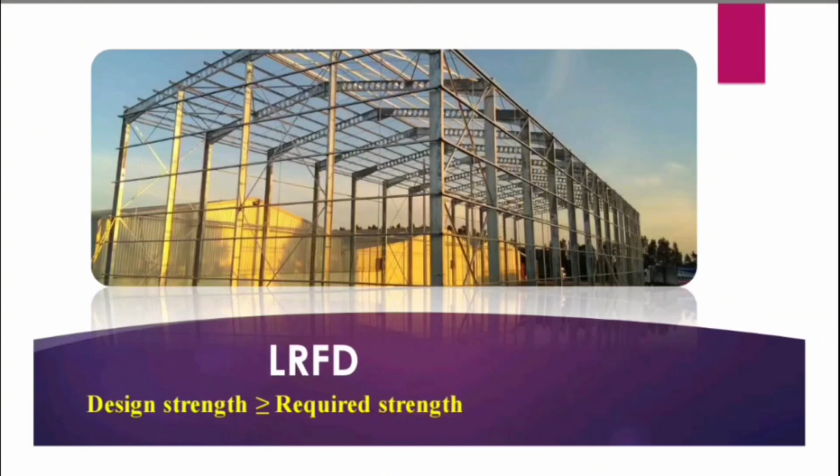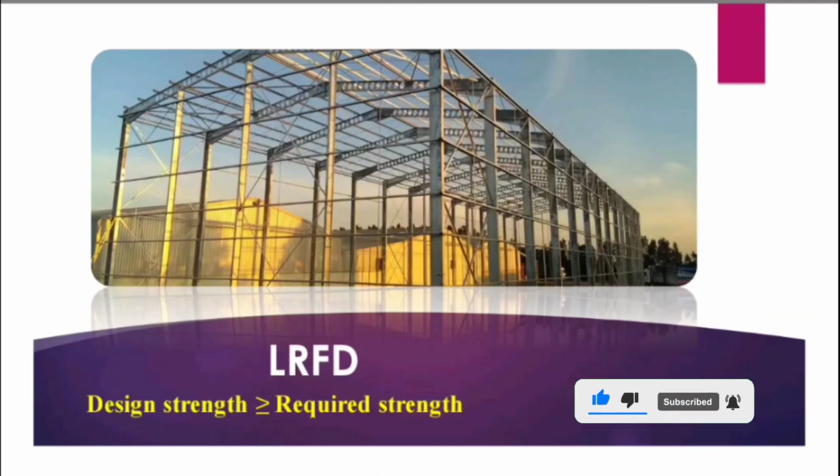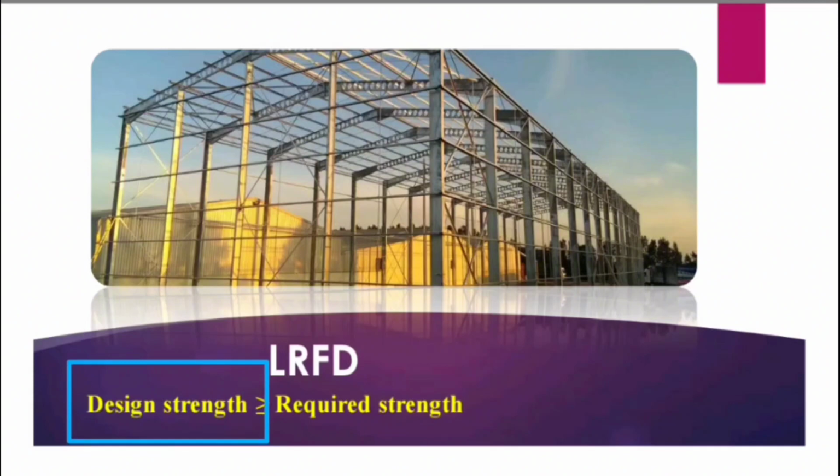LRFD and the plastic design method are both the same, but in the plastic design method we are only using the factor of safety on the load side, not on this side. We only use the factor of safety on the required strength side. We are amplifying the loads. Now in ASD we use the factor of safety on the design side. We divide the nominal strength by a factor of safety to achieve this governing equation.